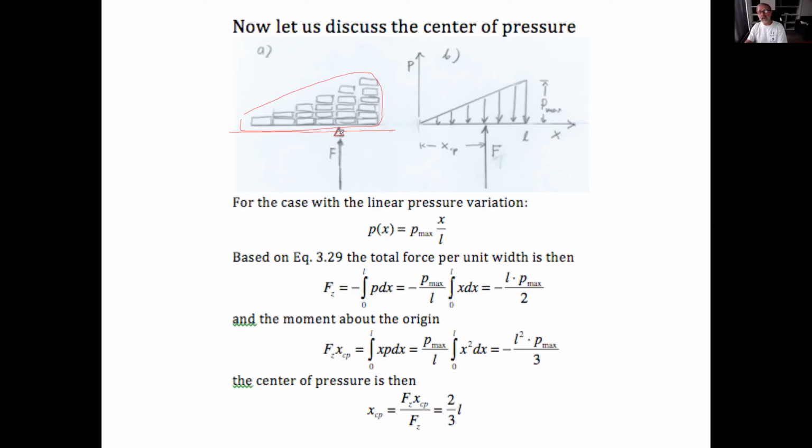The same story applies for a linear pressure variation. And of course, we're going to call that point center of pressure, XCP. That's what we're going to call here. Actually, my drawing should go a little bit more to the right. Doesn't matter, that's all right. So here's an example of how we found it. Now remember, on the side of the pool, the pressure really changes like that. So this is very similar to what we need to do pretty soon, okay?